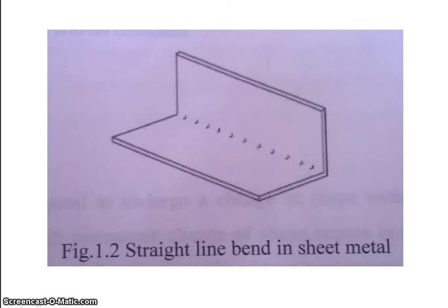Spring back is a major problem during the bending of sheets that occurs due to the elastic recovery by the material, causing a decrease in the bend angle once the pressure is removed. The spring back can be minimized by introducing an excess amount of bending so that the finished bending angle is the same after the elastic recovery. However, a careful estimate of the elastic recovery based on the mechanical behavior of the sheet material is necessary to achieve the same.